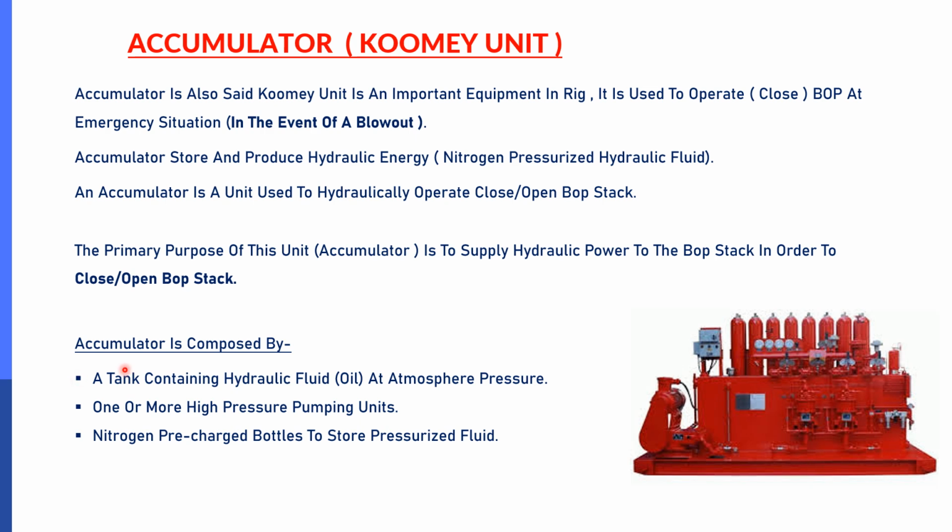Now, what is the accumulator composed of? It is made of a tank containing hydraulic fluid, oil at atmospheric pressure, and one or more high pressure pumping units, with nitrogen pre-charged bottles to store the pressurized fluid.